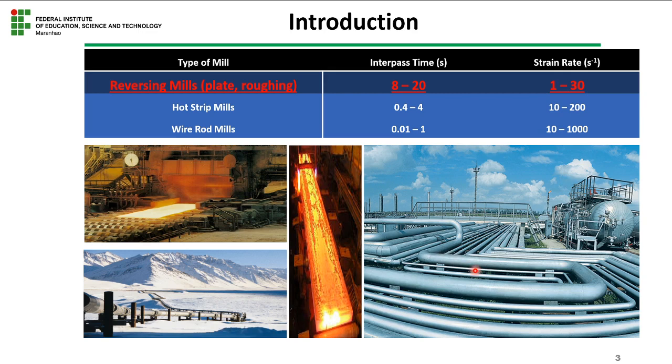Such an approach is, like I said, the thermomechanically controlled processing, and the exact parameters depend on steel chemistry, initial thickness before rolling and final plate thickness, and of course, the capacity of the rolling equipment.